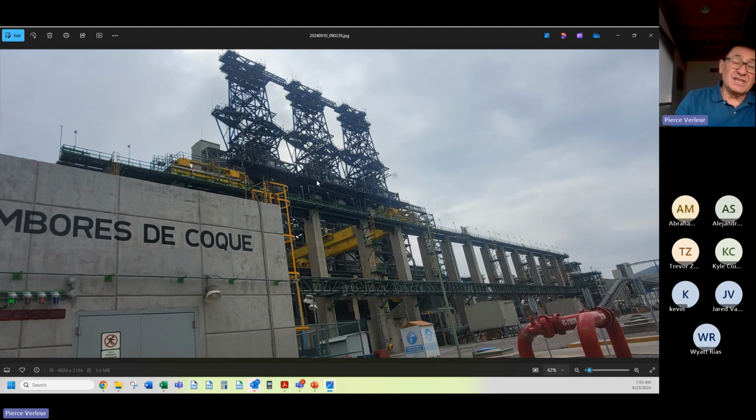The process is called decoking because you're taking the coke out of the cylinder. Once you get to the bottom, this water jet then turns 90 degrees. We're controlling the position of this water jet, I'll tell you how we did it in a second. And then it rotates and cuts the coke out of the inside of the cylinder.